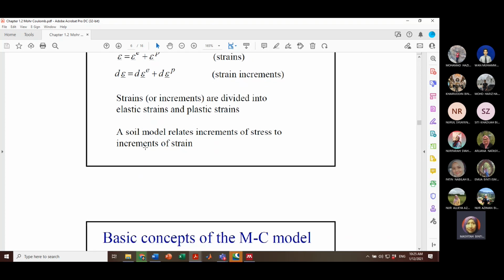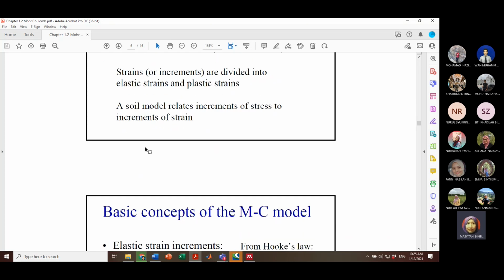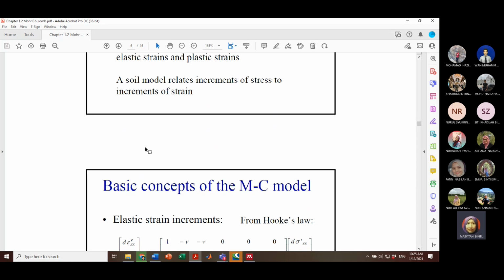I think you need to know the definitions of strain, because strain has a relation to stress. When you apply stress, strain results. How do we relate stress and strain with a constant coefficient? We call it the Young's modulus. So if you don't understand what strain is, there will be a problem. Strain is deformation, the changes before and after relative to the original shape. That's how you can calculate the strain. That's why when you apply stress, there will be strain.